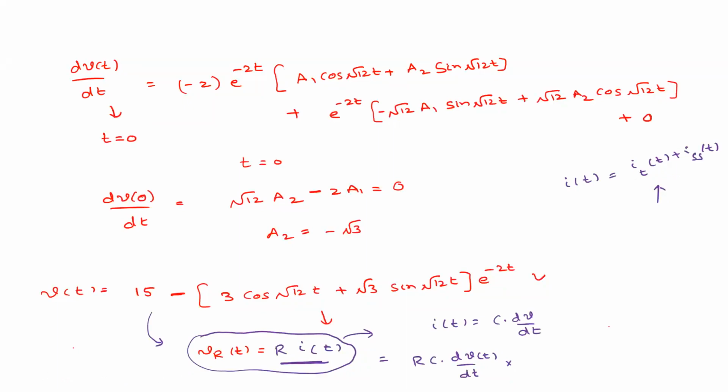So we have another question. The voltage across the inductor will be the difference between the total and all the other voltages, right? Voltage across the inductor is L into di by dt. We need to differentiate two times. Why can't we do Vs minus VR minus VC? It will become complex. What you are asking is, if you want to calculate VL of t, how to calculate that?